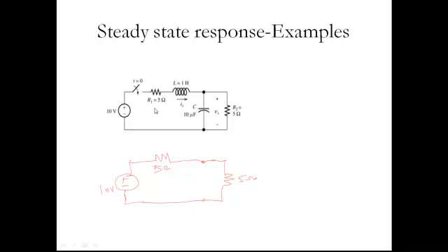So as per this circuit, current through the inductance is also current through R1, this 5 ohm resistance, and the voltage across the capacitance is also voltage across R2, this 5 ohm resistance. So you can solve it. You know very well, this becomes a series circuit, so 1 ampere current will flow. So Ix will be equal to 1 ampere and Vx will be equal to 5 volts.